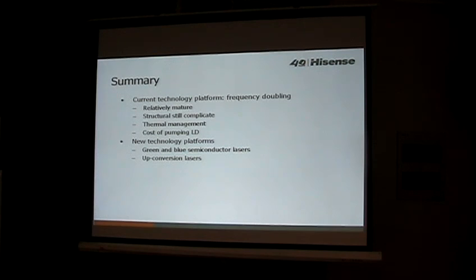Some company sold this erbium-doped amplifier and installed it undersea, but because of the upconversion, they generated a lot of green light. So this green light coincided with some absorption spectrum of the packaging material, so it kind of damaged the package.